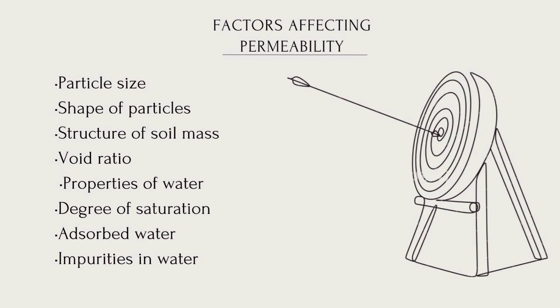The water properties. The various properties of water or fluid, such as unit weight and viscosity, also affect the permeability. However, unit weight of water will not affect much since it does not change much with temperature. But when the temperature is increased, viscosity decreases rapidly.